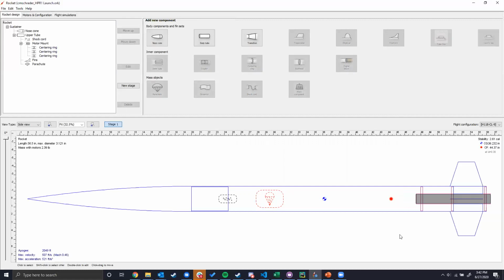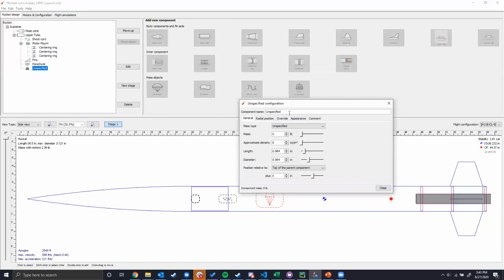Finally, I want to draw attention to some components which I don't have modeled on here. For example, you can notice that I don't have any U-bolts. In OpenRocket, there's no U-bolt component, but what you can do is add a mass component. A mass component doesn't have any particular aerodynamic properties or special effects. It is just there to stand in for some known mass, such as your hardware mass, or possibly a payload or a flight computer that's in here. You can specify the actual size.